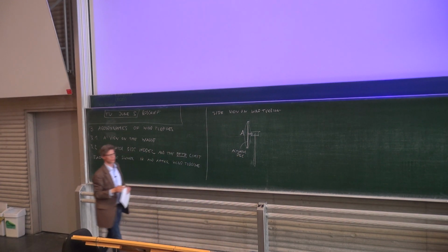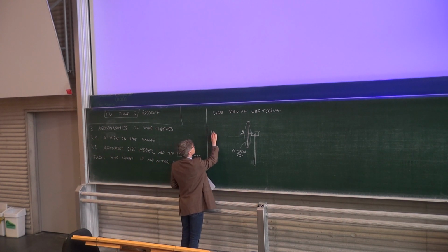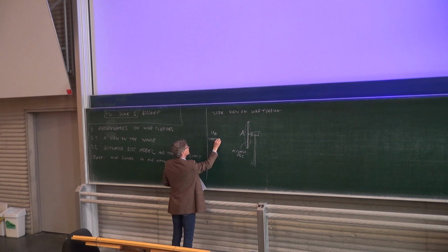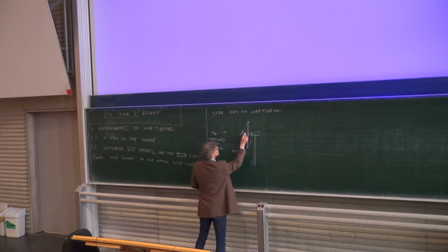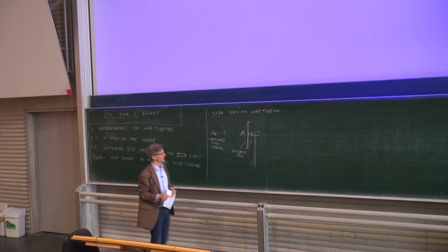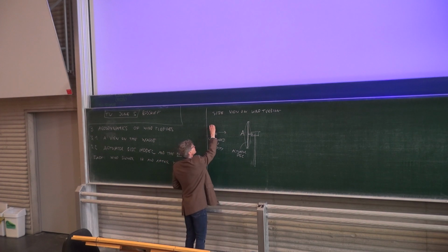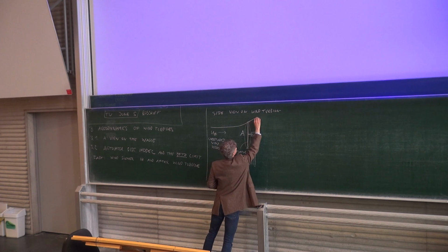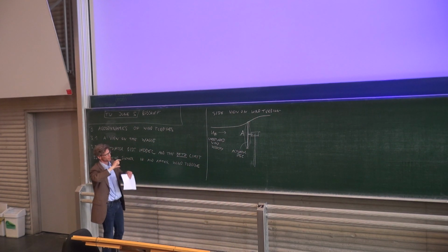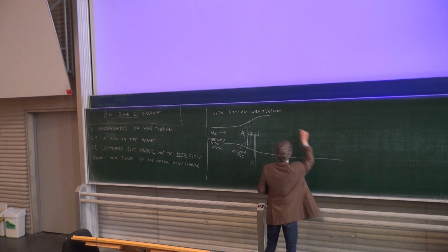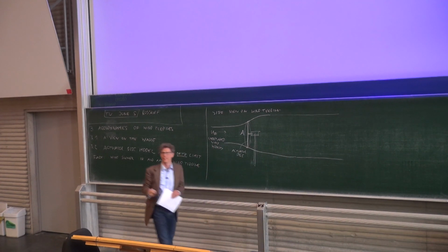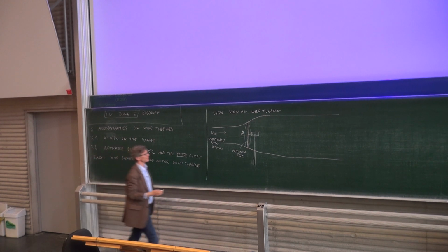And now the question is, what will it do with the flow? There is some velocity here. We call it u infinity, and I call it u0 now. That's the undisturbed wind velocity. Then it will somehow get slower when it goes into the wind turbine. So there will be less wind here, and then there will be a slower speed behind the wind turbine. And that implies, and this is the thing that I want you to note, that air needs to slow down, and that means implicitly that the part of air that passes through our turbine comes from a slightly smaller region, and then once this velocity is constant again, this region becomes big again. So this is how we should imagine the flow through a wind turbine. So it's slower velocity here.